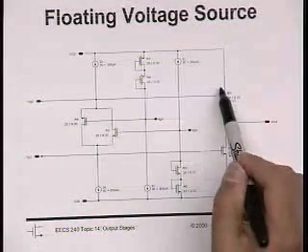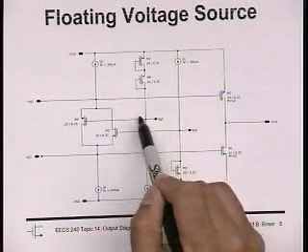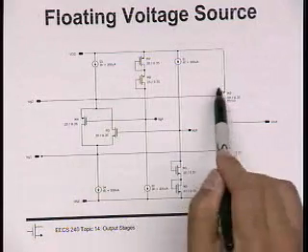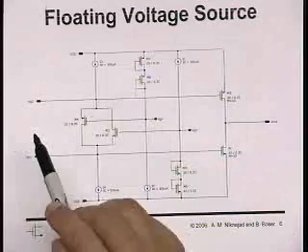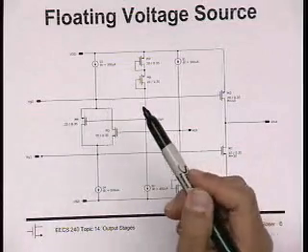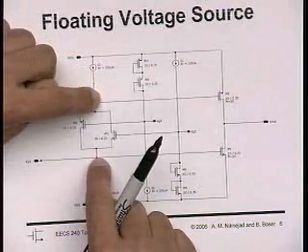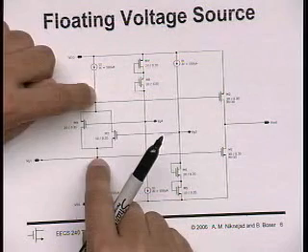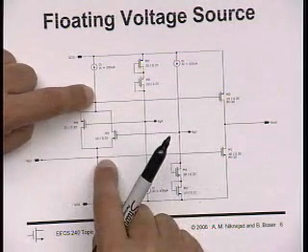Let's look at this device. Same thing. I have 1 VGS, 2 VGS, and then down 2 VGSs, and then up a VGS. So this device is also matched to this device, and these two devices are also matched. And essentially what I've done here is I've accomplished a couple things. I've produced a voltage between these two nodes, right? That's initially what I wanted, was a floating voltage between these two nodes. And I can control that voltage by controlling the currents.